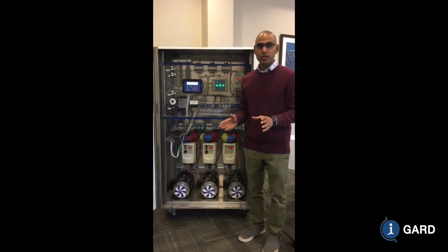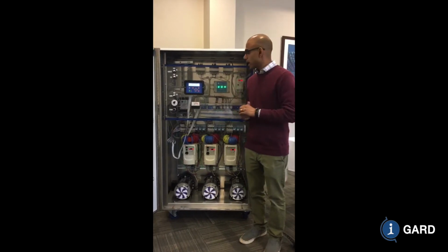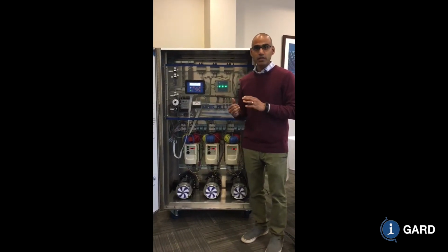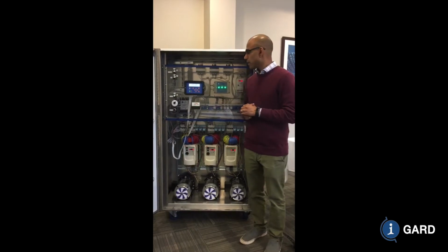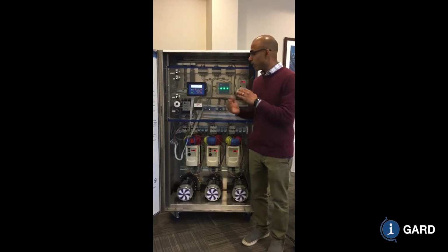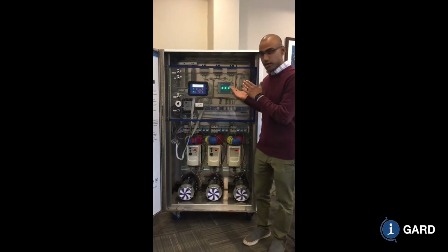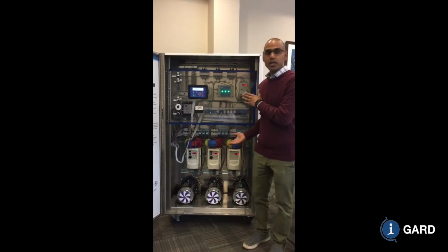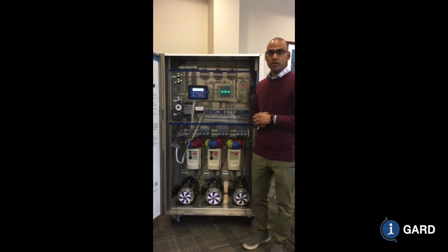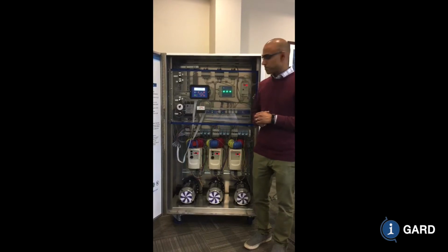Today we're going to discuss the DSP system. It's our I-Gard's ground fault relay system. We're going to discuss it by way of example. We have an example system right here. It's an isolated 208 volt system, resistively grounded.